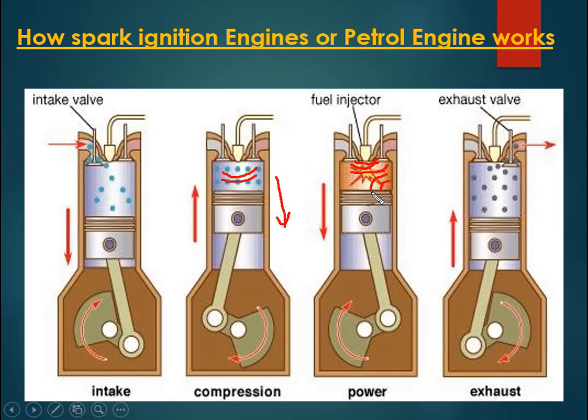Rather, it ignites outside the normal combustion front, and when these two high-frequency pressure waves hit each other, this creates a very high metallic sound called knocking. When the sound is less, it is called knocking, and when the sound is very high, it may be called detonation.